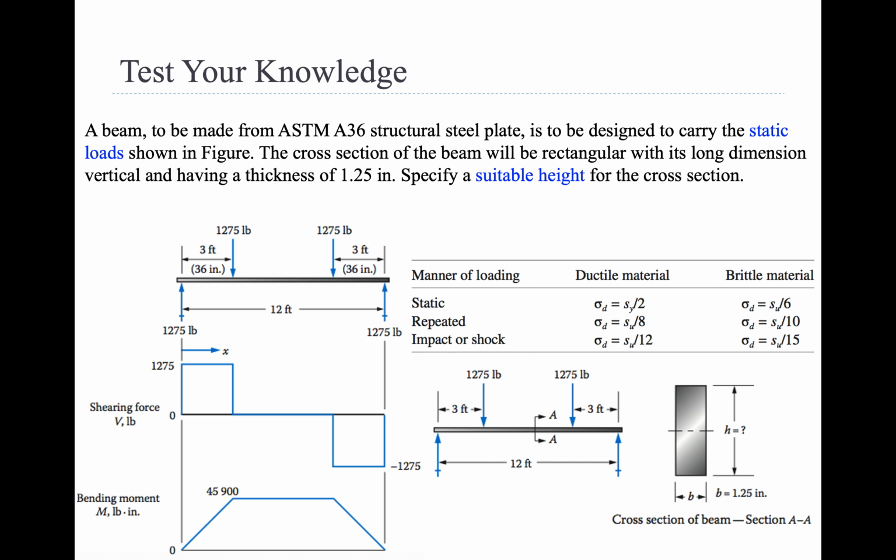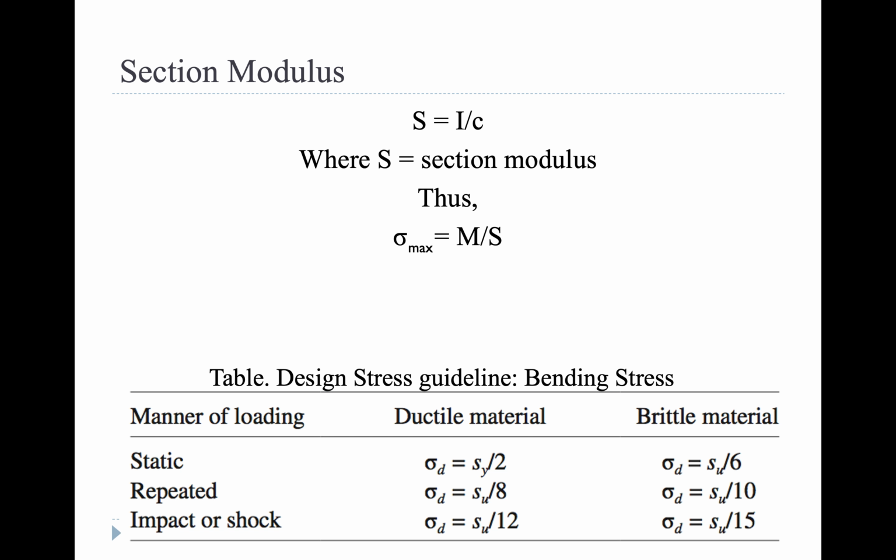Based off of those different types, there are two different kinds of materials in the world: ductile and brittle. Ductile materials are the ones that stretch. You can see them stretch before they break. With brittle materials, you have no clue, and it just breaks suddenly. Glass could just break. You might see some cracking, but it's not getting longer or stretching. It just breaks, right? Ductile materials you can see start to stretch, like taffy or gum. Steel is a good example of a ductile material, whereas concrete is more of a brittle material.